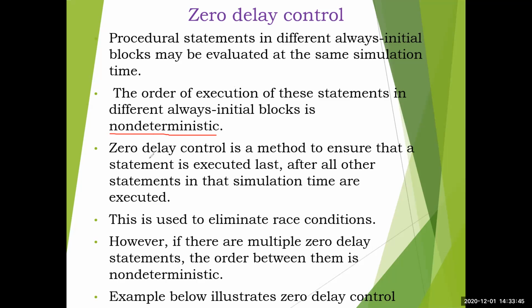Okay. So that's why zero delay control is a method to ensure that a statement is executed last. Just to make this statement executed last, we will exercise zero delay control, and it is not of any practical use. Okay, not a recommended practice, just to show you the concept we are discussing here. Okay, after all other statements in that simulation time are executed. So to execute last, zero delay control is used.